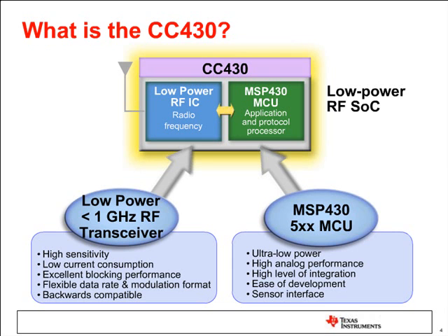So we've got an ADC12 on this part, sampling up to 200 kilosamples per second, and comparator B, shared analog reference, and we'll talk to the block diagram a little later, but high degrees of integration that really simplify your application in terms of other components needed, and hopefully end up reducing the overall cost of a customer design. But what I hear from a lot of customers about the MSP430 is they like how easy it is to use.